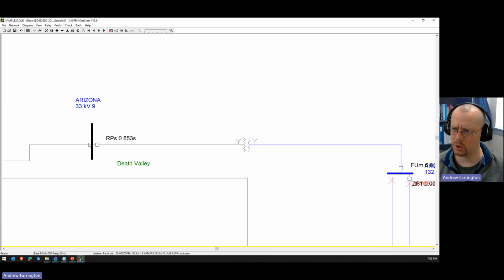important. So if we have a fault here, we want this to operate first because it helps with restoration after the fault. If somebody were to go out here and try and figure out what happened, they would see that this fuse blew first and then assume that the problem might be in the transformer. Transformers are really expensive, and it might be difficult for them to find the fault in the transformer. Obviously, you might have to do an inspection or whatever, right?